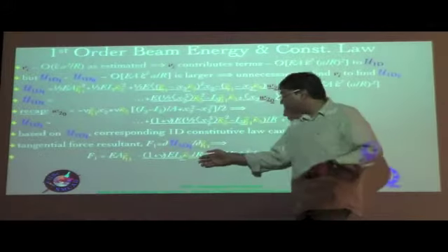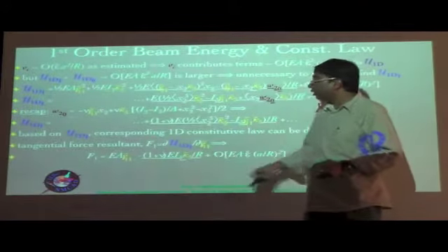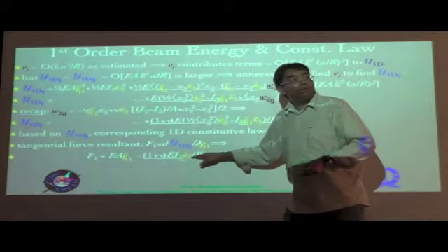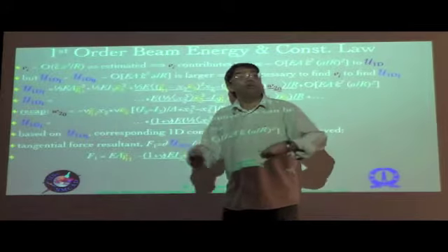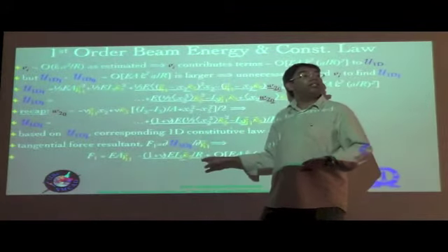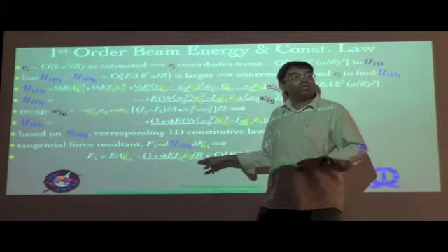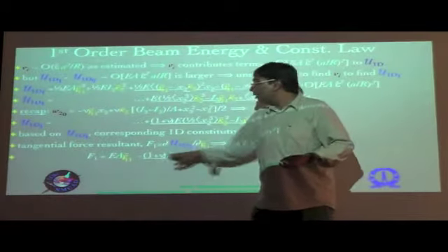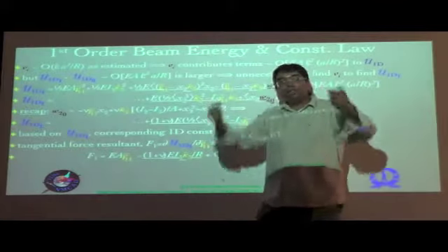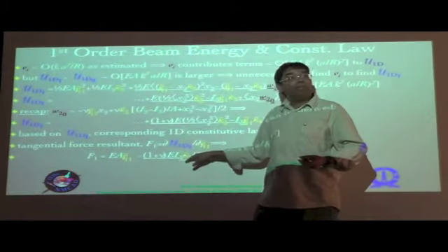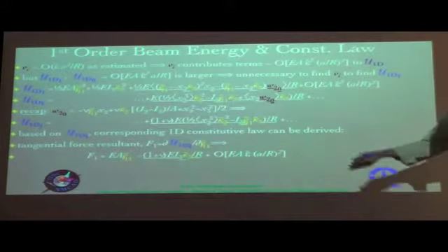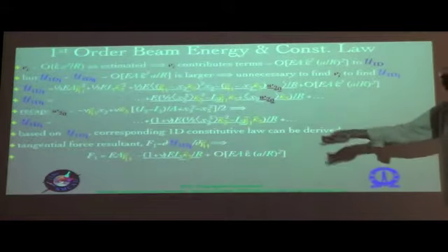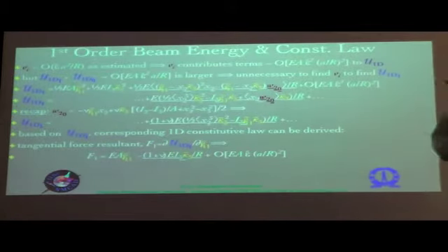Now what happens is in the first order approximation, you get an additional term which is contributed by the bending as well. In other words, bending contributes to the section force, and that is because you had an initial curvature. If you didn't have an initial curvature, your R would have been infinity and this term would not have existed. So that initial curvature is making the bending curvature contribute to the axial force resultant. You will have a similar corresponding relationship when you go for M3 in terms of gamma 11 bar as well, because this is a coupling term which will be present in both.